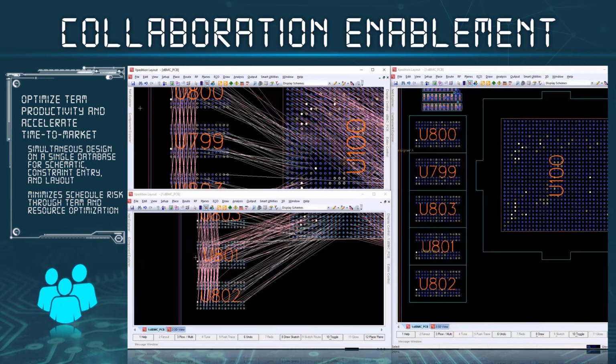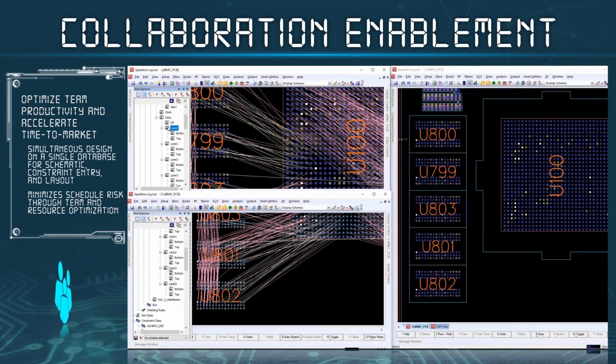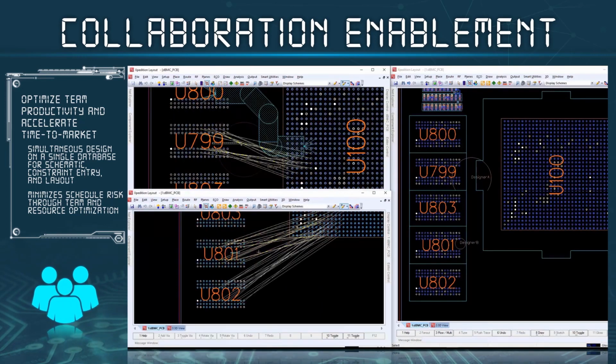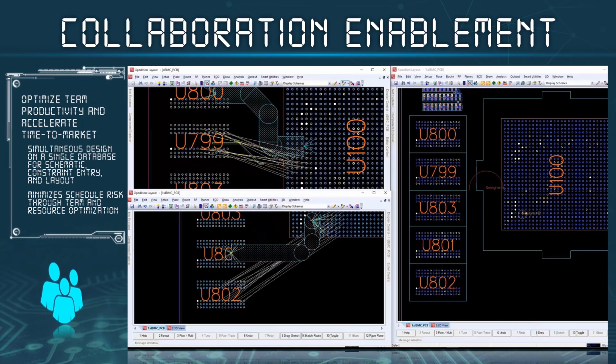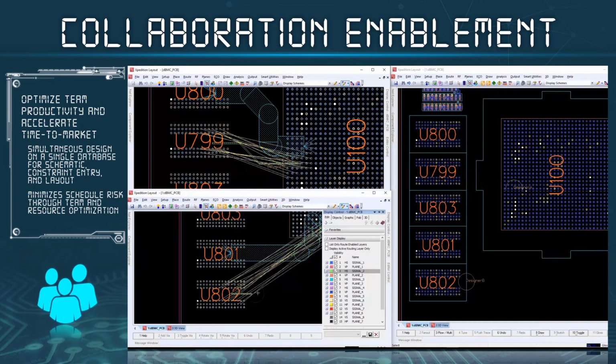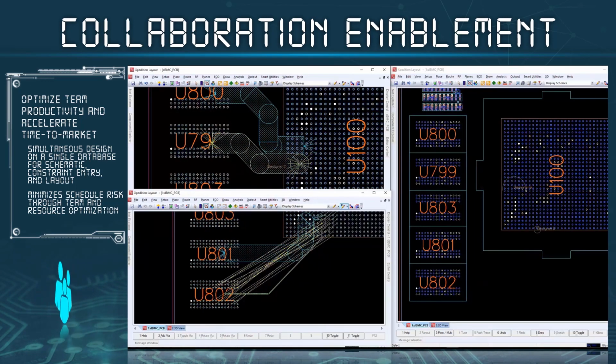At this point, the two users on the left are ready to start performing sketch planning. Sketch planning allows the designer to define where a group of nets will be routed and the layers that will be routed on. In this example, they are defining the paths for the data nets from the DDR memory to the processor, alternating between layers 3 and 5.